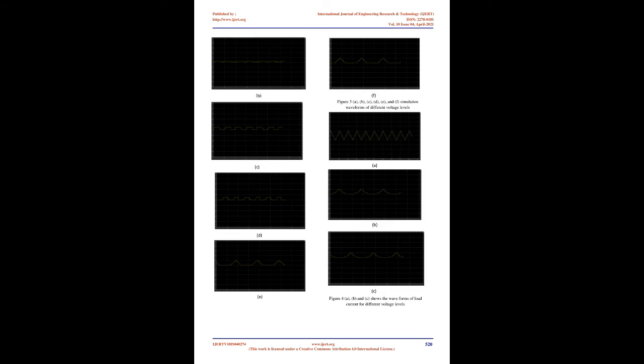A number of common SC topologies are analyzed, including Dickson, series parallel, ladder, Fibonacci, and doubler configurations. Through comparison to simulated results, as well as experimental work, the proposed method is validated and a family of high-performance SC converters is obtained.